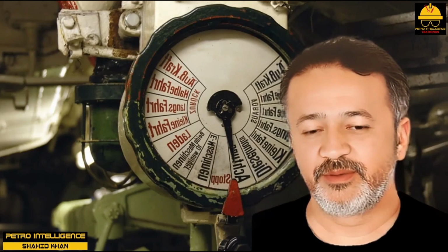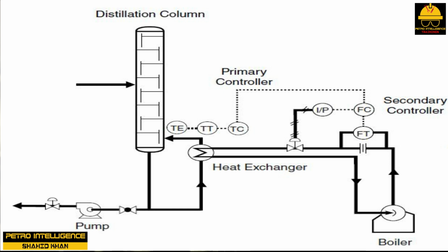Temperature control loop. This picture is a simple layout for a temperature control loop. In large, fired heaters, a temperature measurement is taken at the furnace or from the exiting charge. The primary sensors used to detect temperature are thermocouples or RTDs, often called temperature elements. Temperature elements are linked to transmitters, that is, devices that sense a process variable and produce a signal that is sent to a controller, recorder, or indicator.